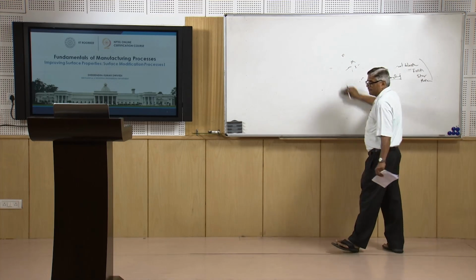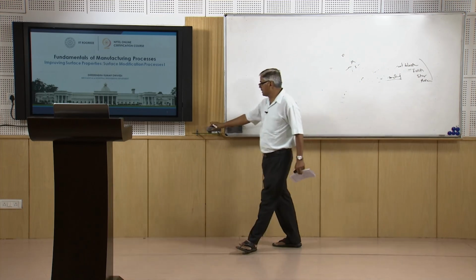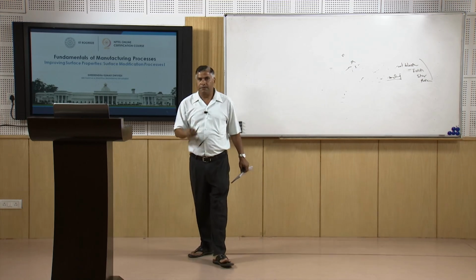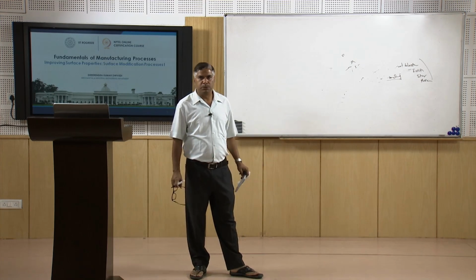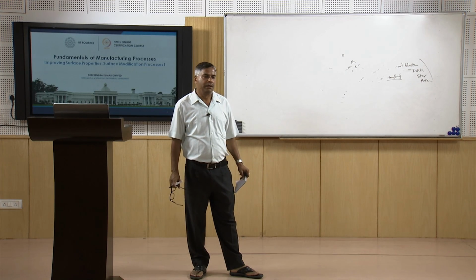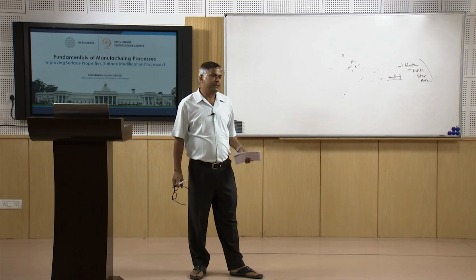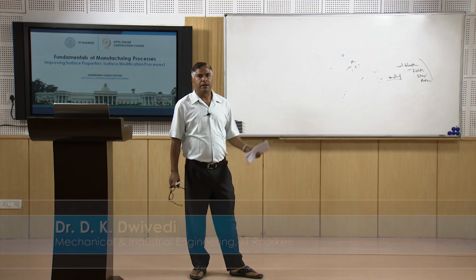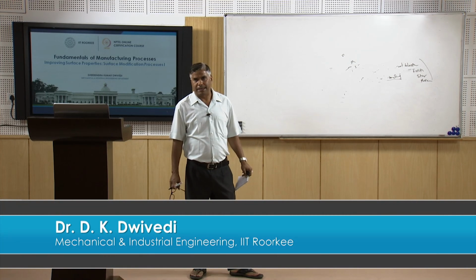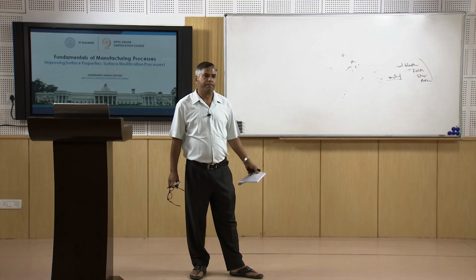So, now I will summarize this presentation. In this presentation I have talked about a category of methods wherein there is no need to change the composition of the surface layers. Simply by transformation hardening, grain refinement or work hardening approaches, the surface layers can be enhanced in terms of mechanical properties for improved performance and improved life of the component.